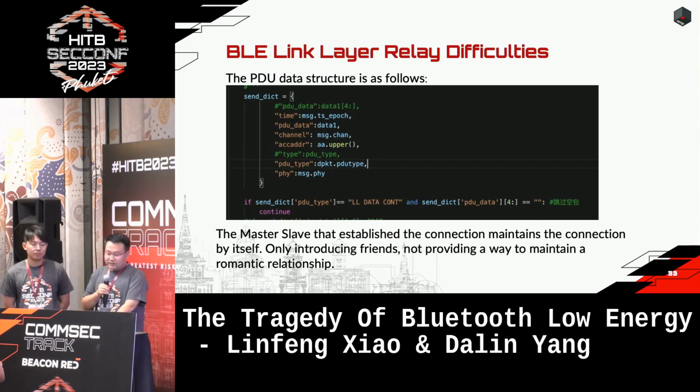Next, this figure shows the packet structures we built, but we don't consider channel map, access address, CRC init, and so on. We relay useful PDU data and classify it, such as link layer control, link layer data, and empty packets.